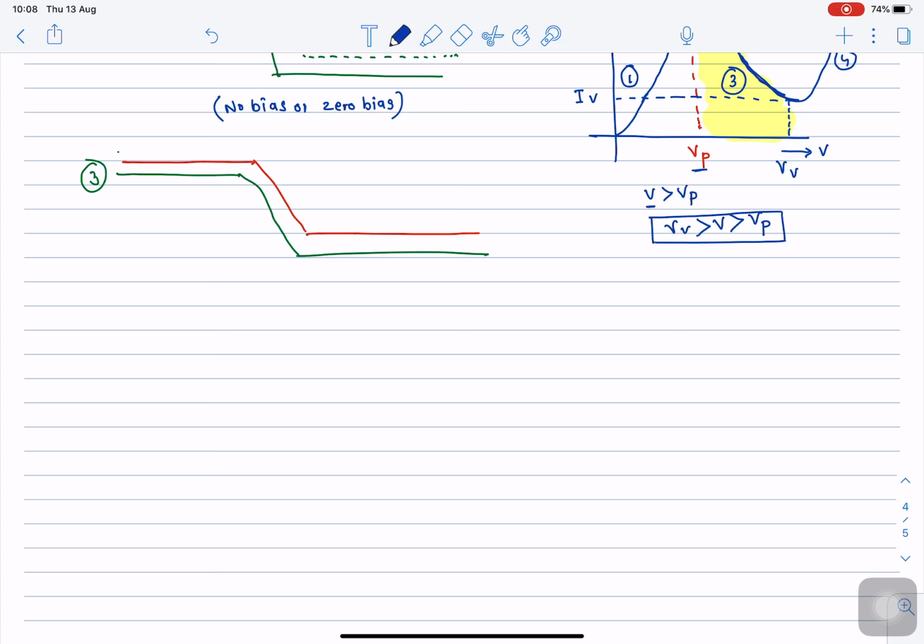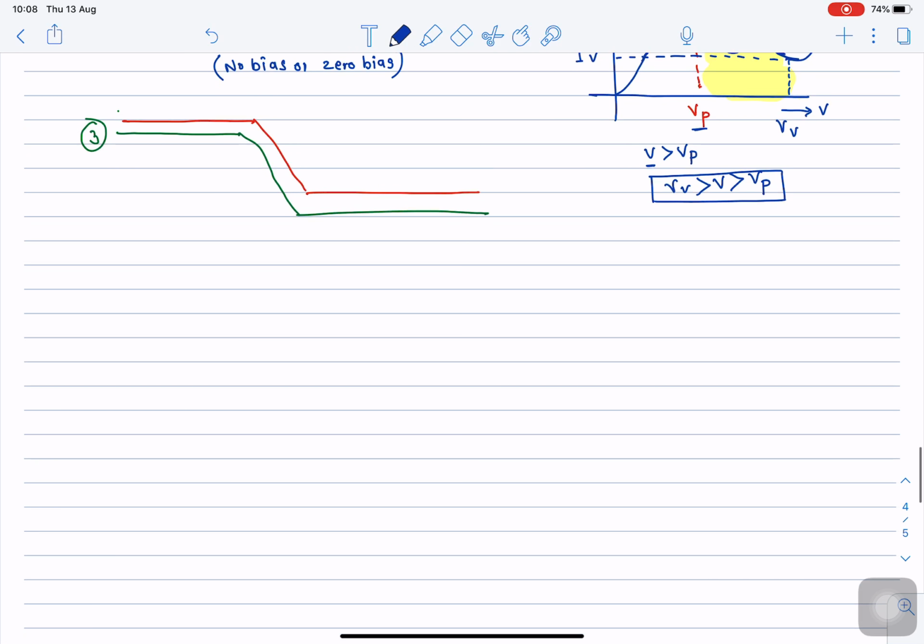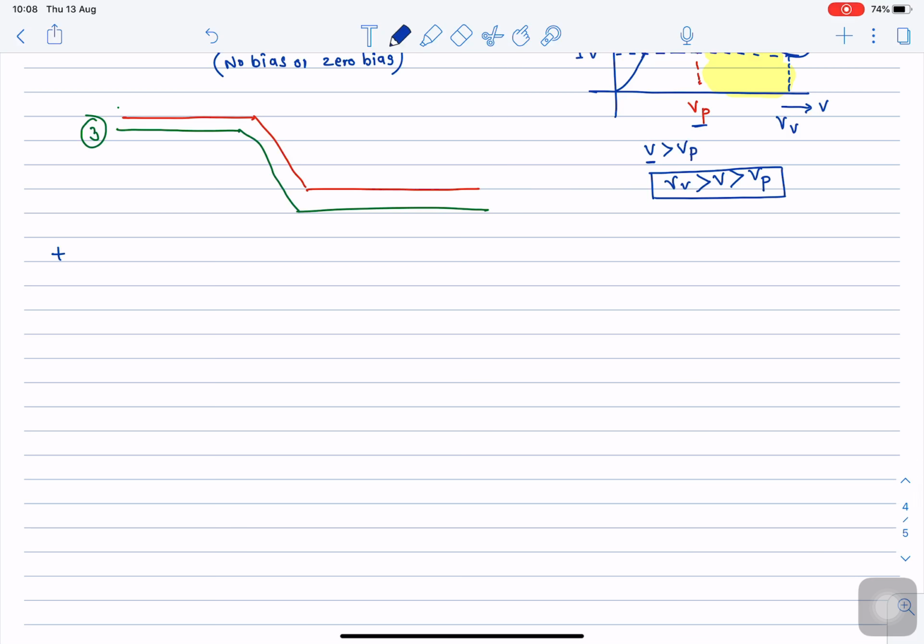Let us see one particular application as an amplifier and oscillator. Here I will draw a block diagram where we can make use of the tunnel diode as an amplifier. To use the tunnel diode as an amplifier, we make use of a circulator device, which we know from module 2, passive waveguide based junction devices.